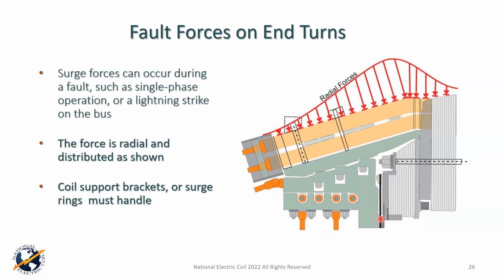You see this black line? This is actually a spring plate that's put in here, and it's affixed here to the step iron and the flux trap, and it's affixed here to the end of the bracket, so that all of these brackets are the same design. It would allow this bracket, along with the whole coil assembly, to move axially, and that's what you would call a decoupled bracing type of system.